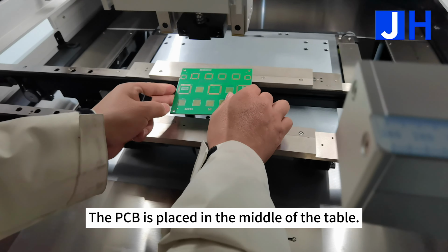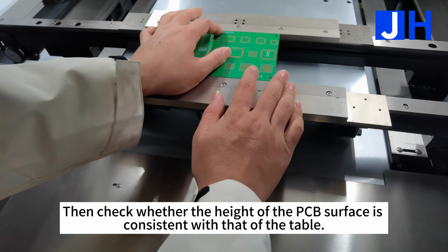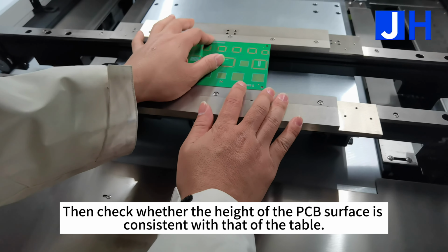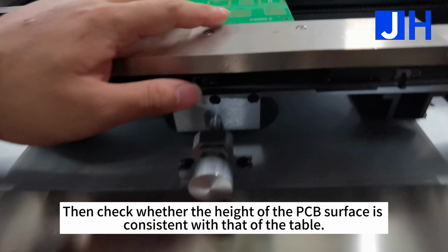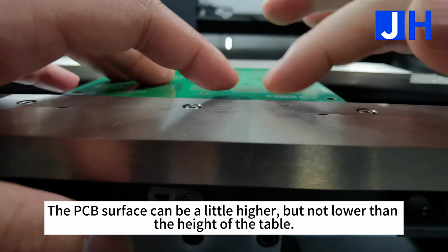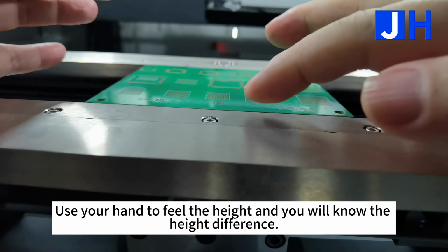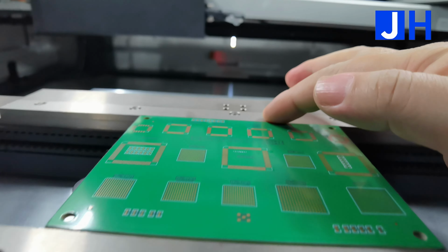The PCB is placed in the middle of the table. Then check whether the height of the PCB surface is consistent with that of the table. The PCB surface can be a little higher, but not lower than the height of the table. Use your hand to feel the height and you will know the height difference.